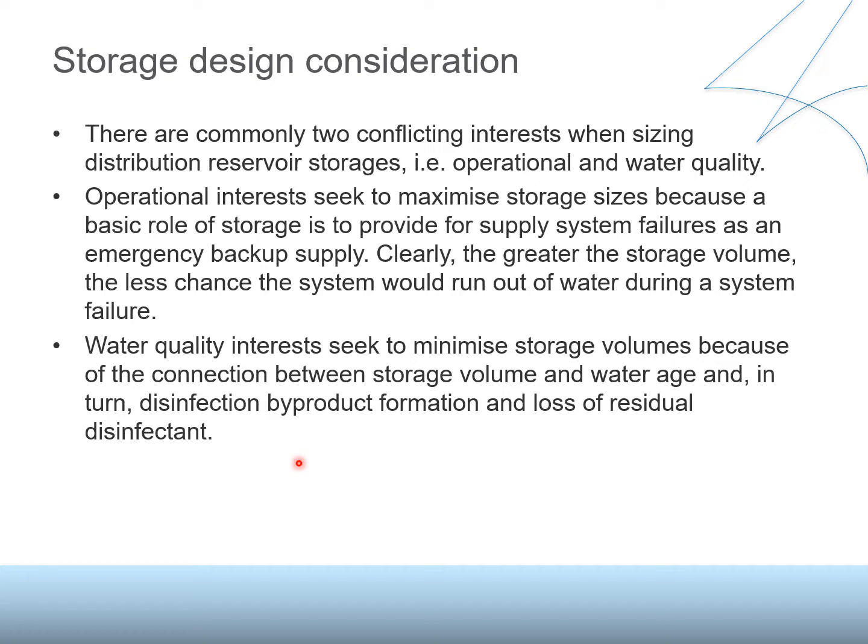If the water stays in the storage tank for long, then it will lose the residual disinfectant, which it should carry up to the consumer's point. So we need to balance these two aspects, from the operational point of view and also from the water quality point of view.